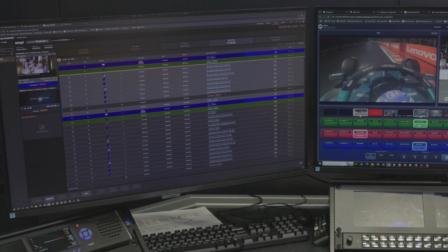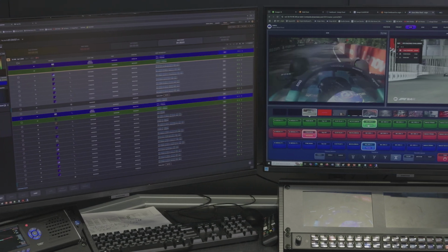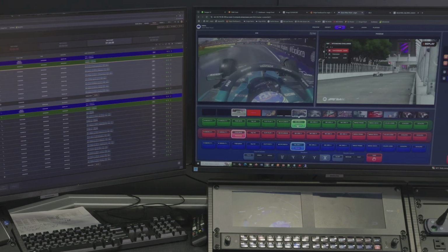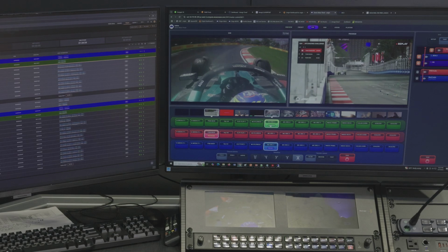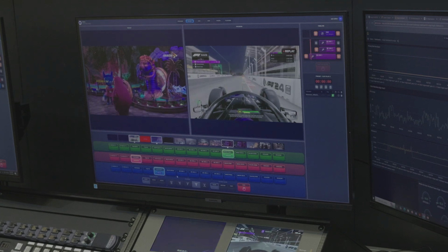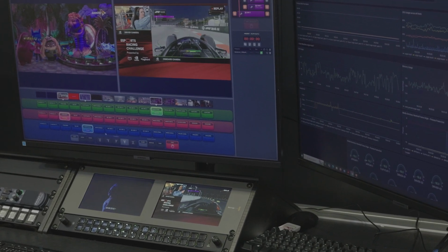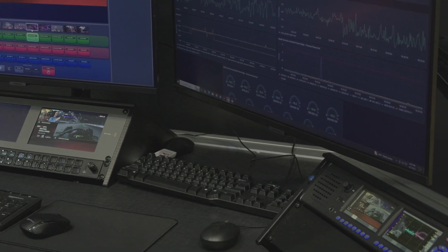So the demonstration here is trying to focus on the concept of having a complete virtualized master control. The solutions we are using here are using a combination of transport streams and asynchronous fabric technologies that allow you to route between signals, not in the transport stream domain, but in the actual frames uncompressed domain. The two master control switcher positions we have here have the ability to do transitions, insert downstream keyers, DVEs, logos, so everything that is required to produce a high quality channel to be delivered to multiple destinations.